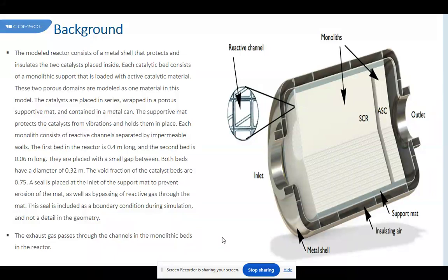Analysis of transient behavior and temperature front propagation. In this section, we review the conditions for back-end and front ignition in monoliths and analyze the impact of conduction in the substrate material on the temperature front propagation. Analysis of the effect of substrate on cold start time. We now present a brief analysis of the effect of the substrate materials on the cold start or heating time.